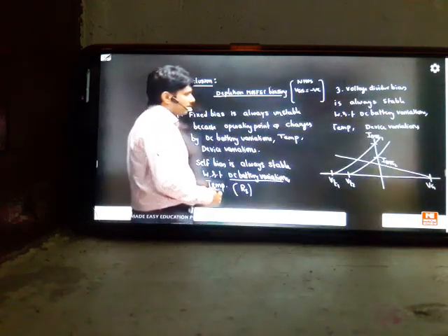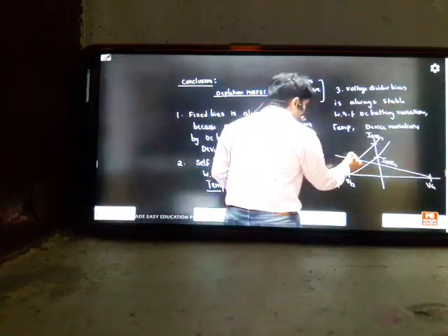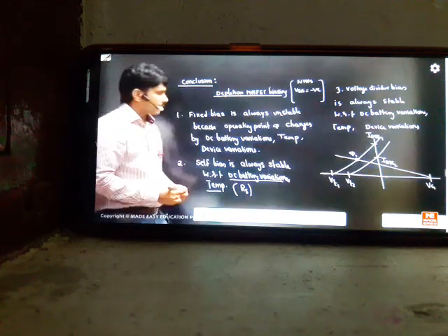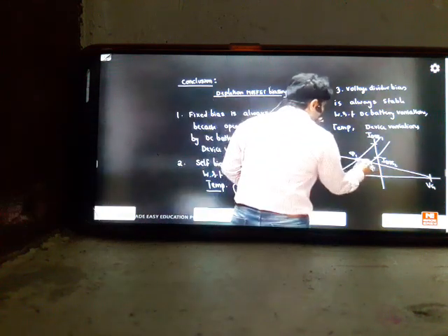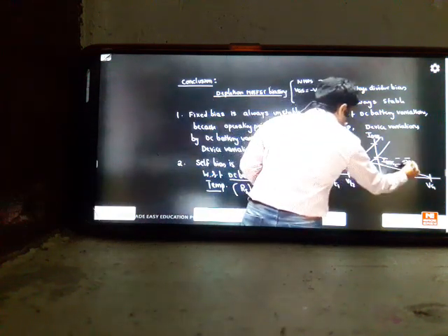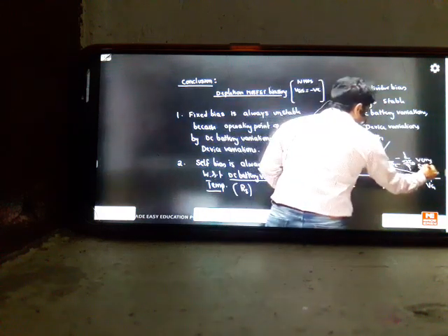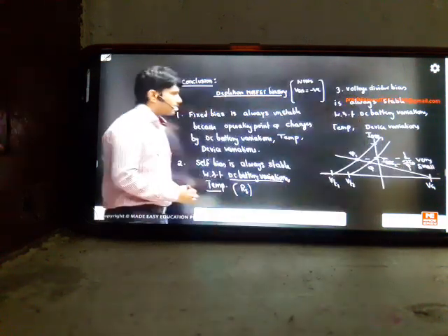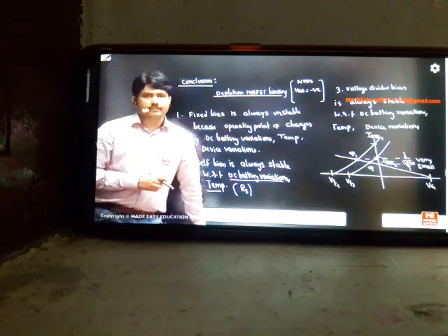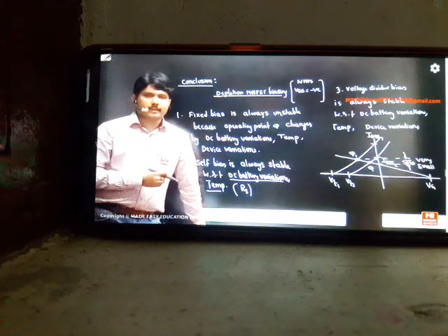Now how do we tell that the device variation is very small? The first operating point is here, the Q point of the first device. The second point is here. For these 2 points, find your del ID value. This del ID change is very, very small in voltage divider biasing. So that is the main reason. The change in the ID current is very small. That's why voltage divider biasing gives good results compared to self bias.